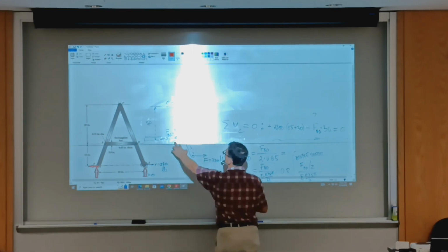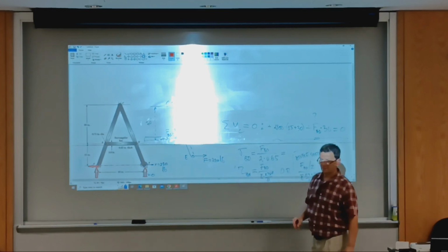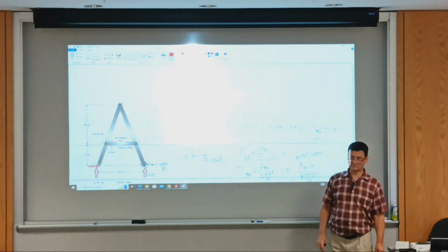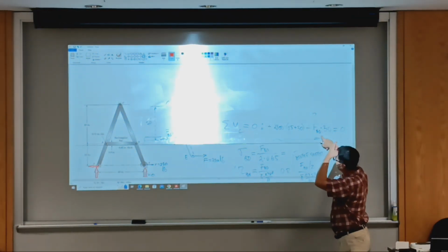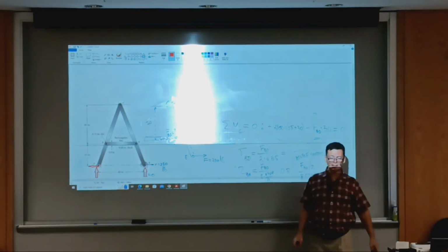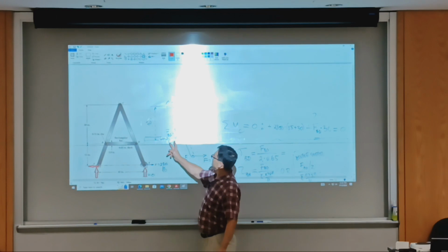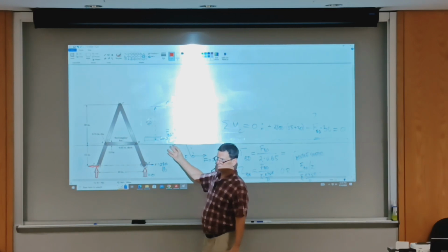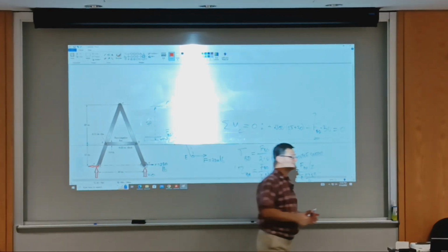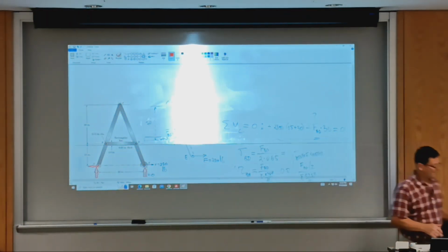So you need to flip it because the sign ended up being negative, and now it tells you that it's tensile. Okay? And only then you proceed to calculate the stress. Because if the sign from the FBD is negative and you carry it here, you get a negative stress, which is compressive, and it does not show the true situation. So you need to make the correction before calculating the stress. Okay, so there are two worlds: the free body diagram and load world, and make sure it's the correct one before you proceed to calculate stresses.